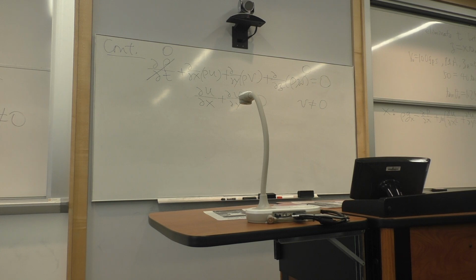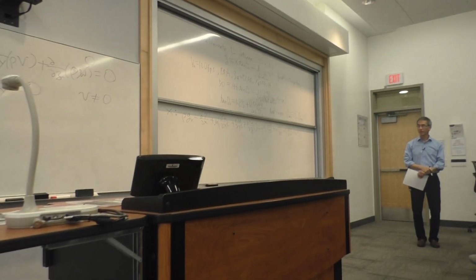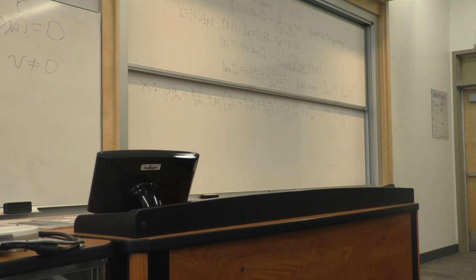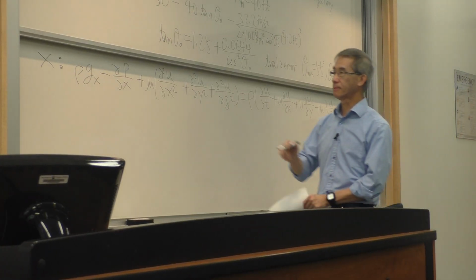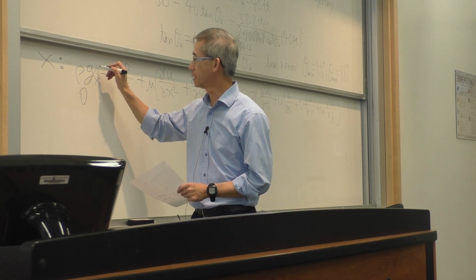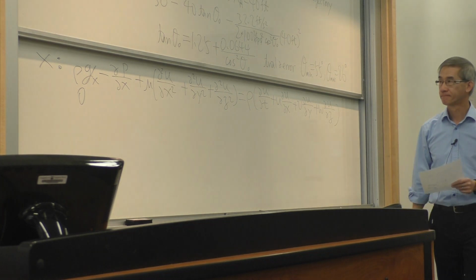So this is the 3D Navier-Stokes equation that accounts for viscous effect. Now tell me how you will simplify it based on many of the lessons you learned from your homework. Starting from left, marching down to the right. 0. 0 for what? Gx. Gx is 0. Very good. Because the gravity is only vertical in the y direction, and I don't care.